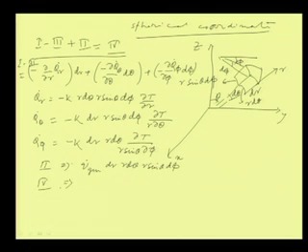And term 4 is the rate of change of internal energy, or rate of accumulation, which is again the total volume dr r dθ r sin θ dφ into rho into Cp into ∂T/∂t.